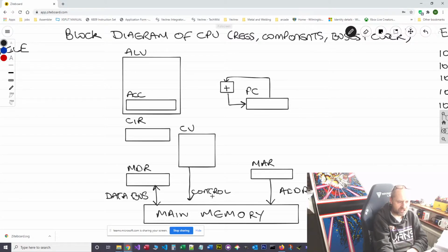So that's how it issues all its edicts of saying you transfer this value from the program counter to the memory address register. We don't need to worry about the complications of that, but what's involved is things called latches and enables. Latches make information flow from a register onto the internal data bus, because all these registers are joined together.